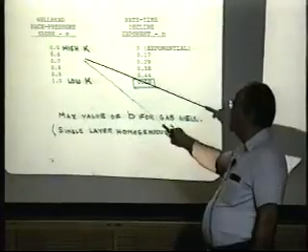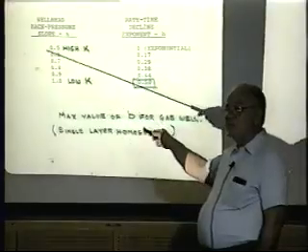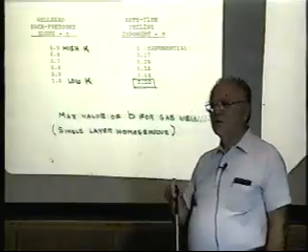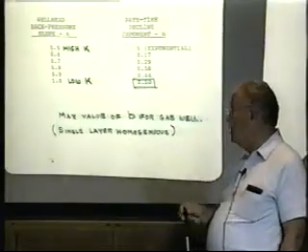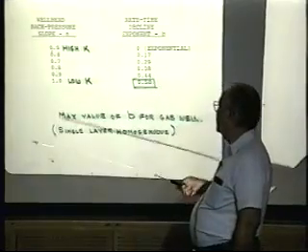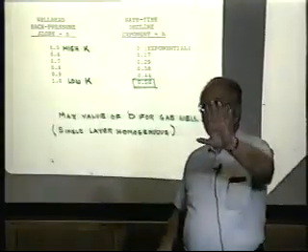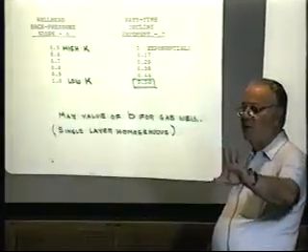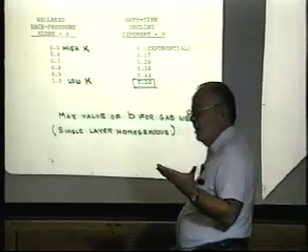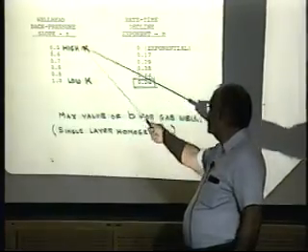I can go even further, and I'll tell you, if you've got high permeability, the turbulent flow effect is going to be dramatic in a reservoir, and you're going to have a problem sizing your tubing because of very high capacity. You're going to be tubing limited, and combining the bottom hole and the wellhead deliverability, you're going to end up with steep slopes. So you tell me the level of permeability. I don't even have to know the exact number if it's high. Well, what's high? 500 millidarcies, a darcy, that's the slope you should expect.